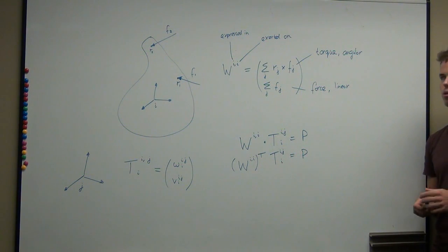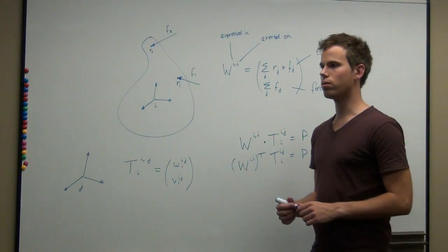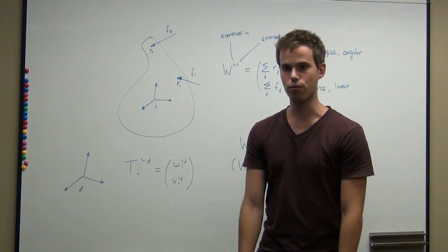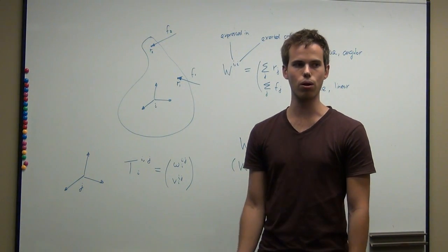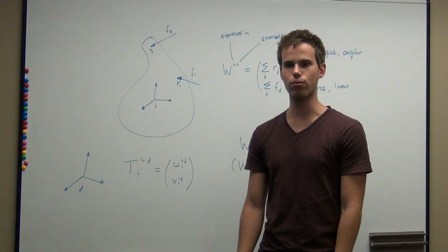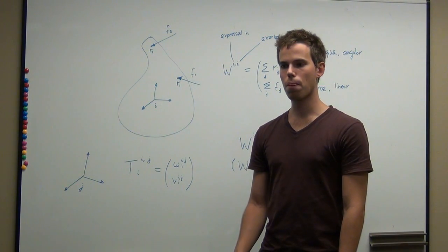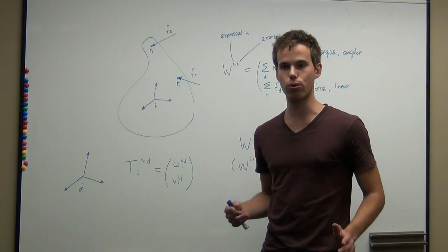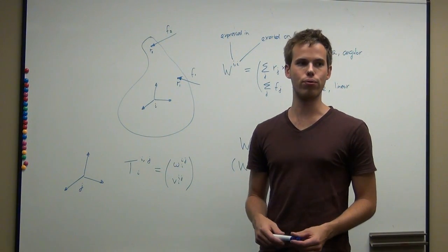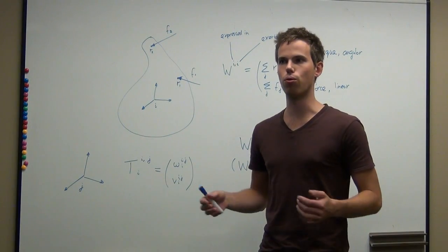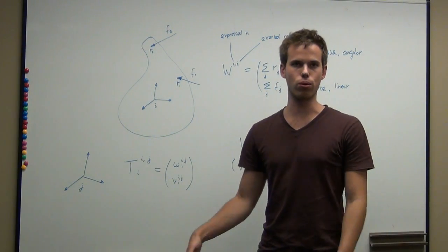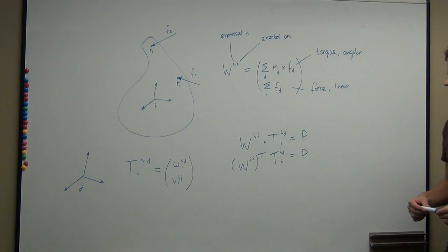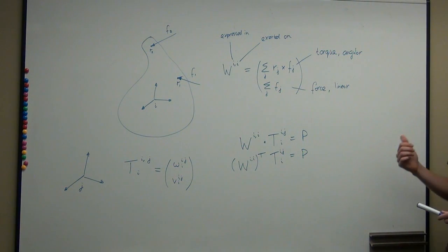So that makes sense. For example, if you have a robot that's standing on the ground, so there are wrenches exerted on both of the feet, you can actually sum up all of the wrenches, even if they're exerted on different bodies, as long as they're in the same frame. And then the result, the total external wrench on a body, is actually the same as the rate of change of momentum of the robot as a whole, even though there might be joints and joint torques. But we'll get to that later. Alright, so that's one property.